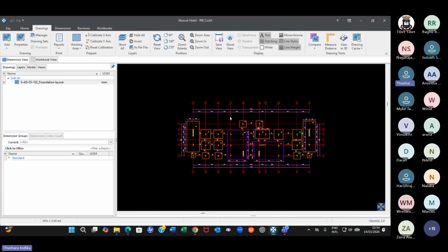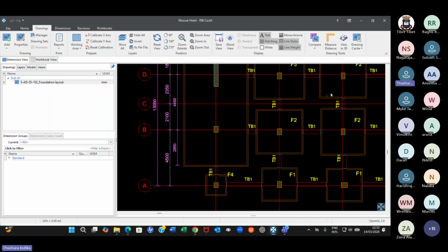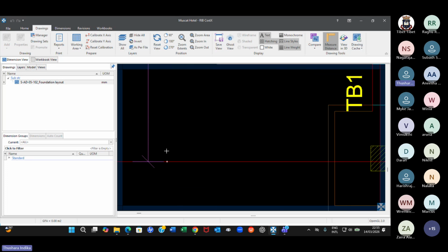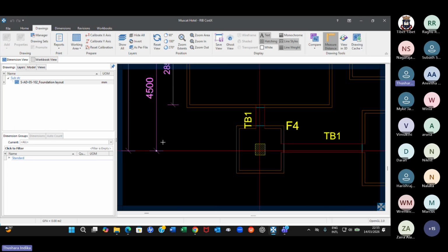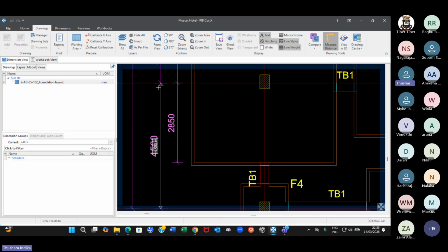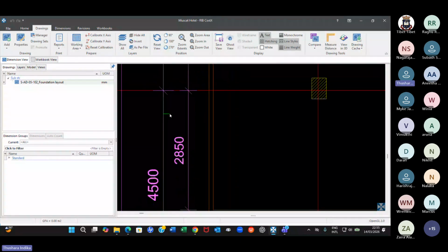And if you are not sure, you better check y-axis coordination now, because anyway you use x-axis calibration for the y-axis. So let us double check y-axis measurement, right? And measure and see whether you are getting the same thing here. Yeah, for 4.5 meters. Perfect. You can see here perfectly. You don't have to click it, okay? When you click, it disappears. Right, you just escape and then do it again.